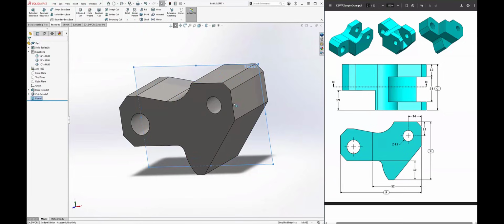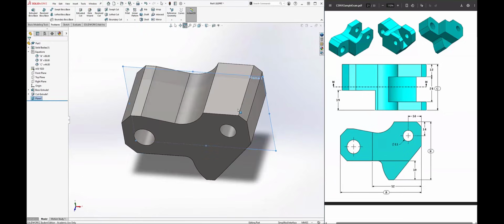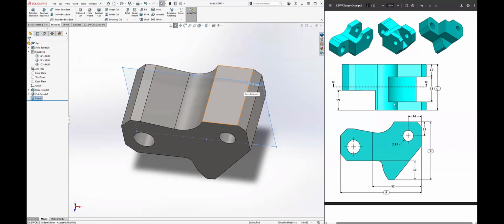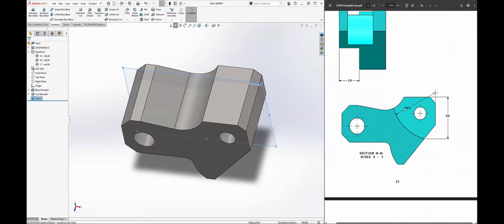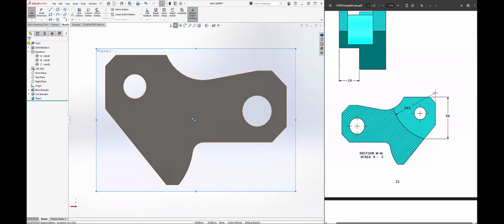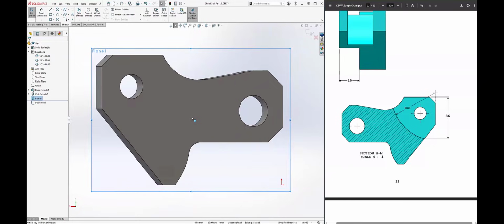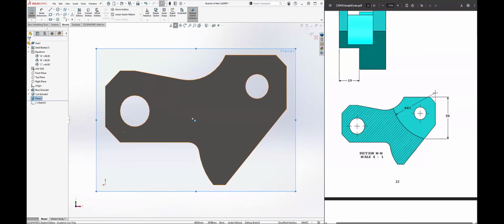So now if we create a sketch, we can easily cut in towards ourselves and cut out that arc right there. So let's take a look at the dimensions of that. That is a 41 around this whole thing. All right, let's open a sketch on this plane. Now it went to the opposite side, but don't worry, if you do Control 8 again, it actually switches normal to and does the other side. So you can always flip the side you're looking at depending on what you're doing.